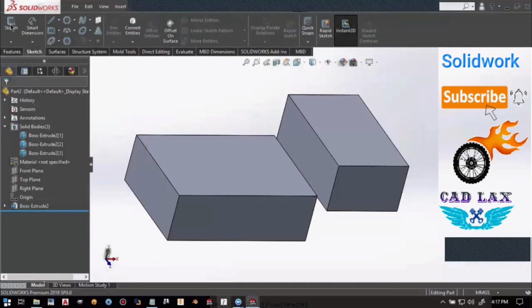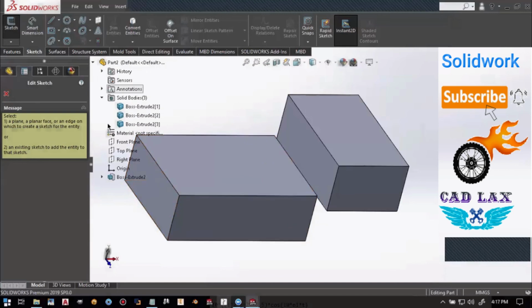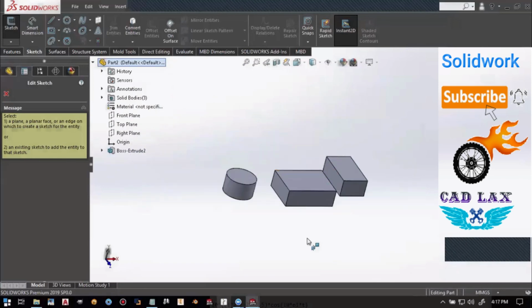So if I take sketch, I can select either these three planes, front, top, and right, or any flat face that exists in this graphics area. There are a lot of faces: six faces here, six faces here, and two more, so around 14 faces.